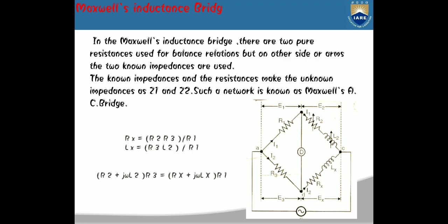A Maxwell bridge is a modification to a Wheatstone bridge used to measure an unknown inductance, usually of low Q value, in terms of calibrated resistance and inductance or resistance and capacitance. When the calibrated components are a parallel resistor and capacitor, the bridge is known as a Maxwell-Wien bridge. It is named for James C. Maxwell, who first described it in 1873.